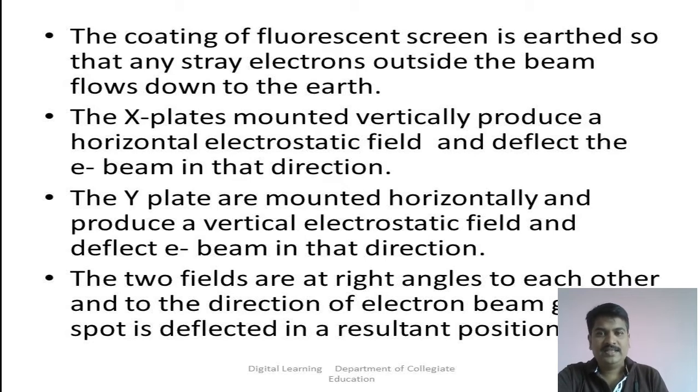So next is the third part, which is the X plates. X plates are mounted vertically and produce a horizontal electrostatic field and deflect the electron beam in the horizontal direction.